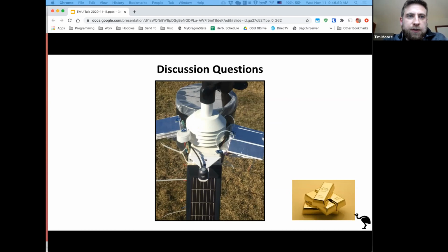And again, this comes back to what we saw with the HOBO temperature sensor, where you're trading off the fact that the sensor unit is completely waterproof with the fact that it can lead to inaccurate measurements of temperature if the air inside it heats up and then takes a while to cool down.